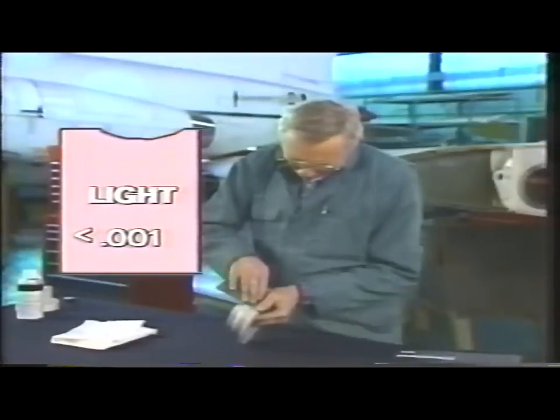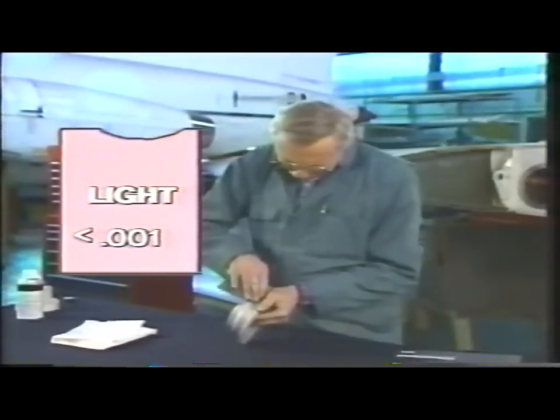Light corrosion is distinguished by discoloration or pitting to a maximum depth of 1/1000th of an inch. This is about 1/4 the thickness of an ordinary sheet of copier paper. Light corrosion can normally be removed by hand sanding.